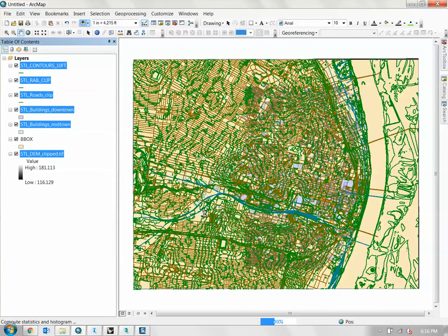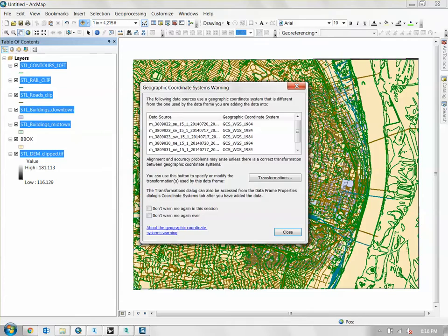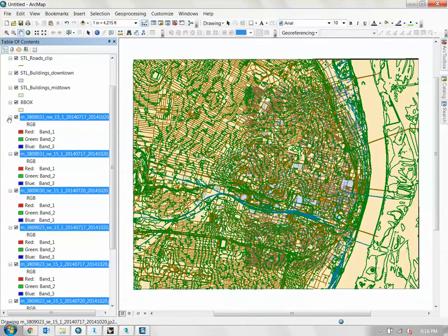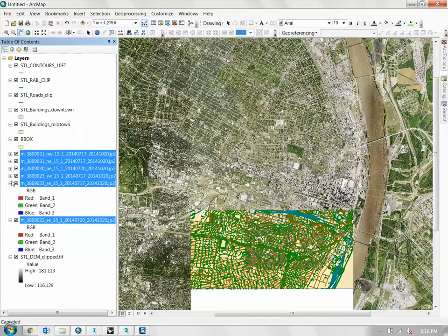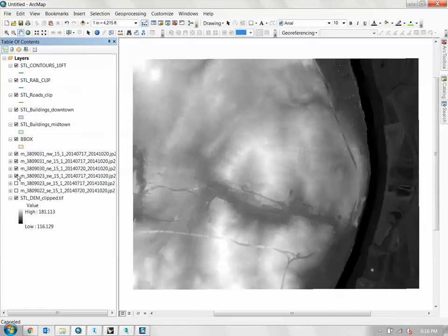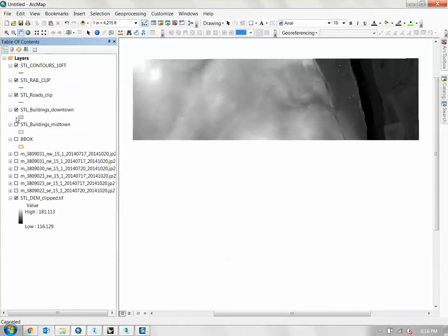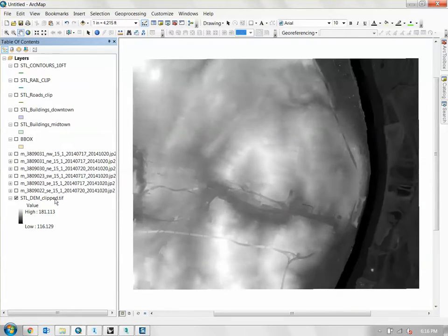And what we're going to do is just use this as a reference data frame to see what information we're going to start bringing into Infraworks, so we can do our 3D modeling in Infraworks. But just to recap some of the basics in Infraworks: if you have a DEM image here, this is basically the terrain information that, once you bring it into Infraworks, will immediately turn into a 3D model for your site.